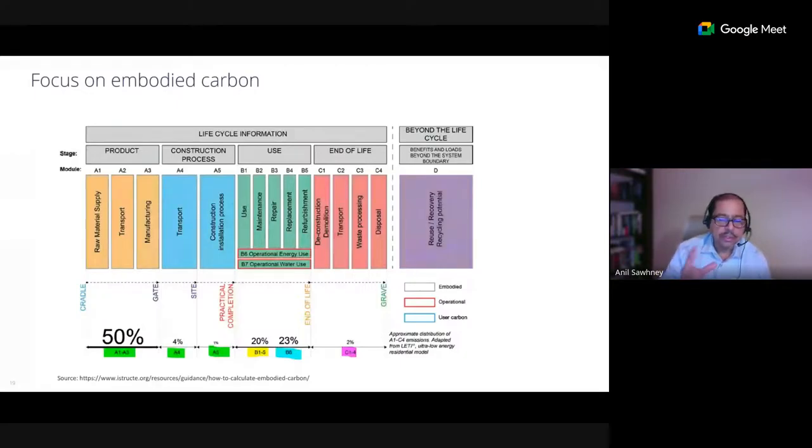What we are trying to do is assume that you're doing a WLCA for a concrete RCC column. If you knew the quantity of concrete, the quantity of steel, and the carbon factors for concrete and steel, meaning 1 cubic meter of concrete releases how much CO2 equivalent,